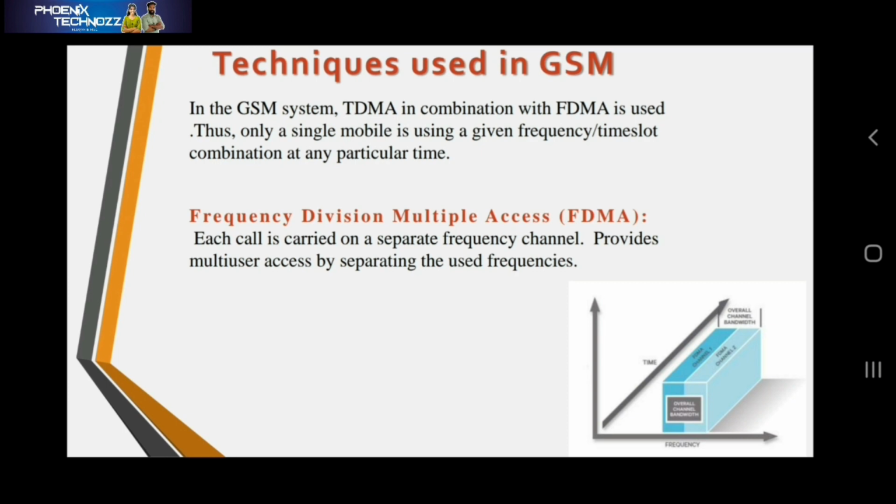In frequency division multiple access, the bandwidth is divided into different orthogonal frequency bands, and each frequency band is given to a different user for sharing the communication resource for the entire time duration. That is, the communication resource is shared among the mobile devices for the entire time duration, but with different orthogonal frequency bands.